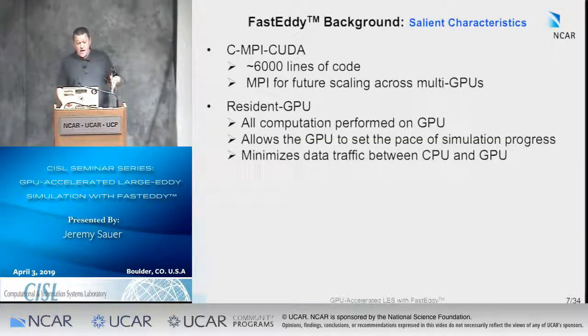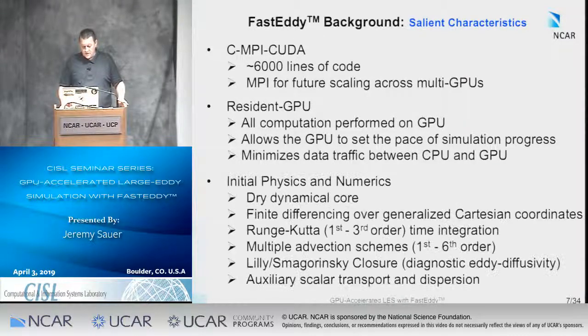It's built as a resident GPU algorithm, and what we mean by that is that all of the computation, all of those terms in the governing equations, are solved on the GPU. We want the data to live down there and the next state of the data to stay on the GPU. This allows the GPU to set the pace of simulation progress rather than waiting on the CPU, and it minimizes data traffic between the CPU and GPU.